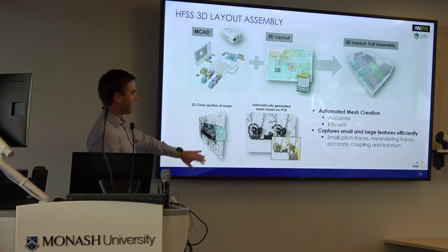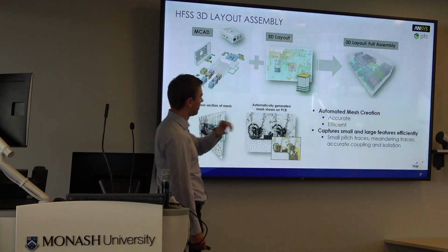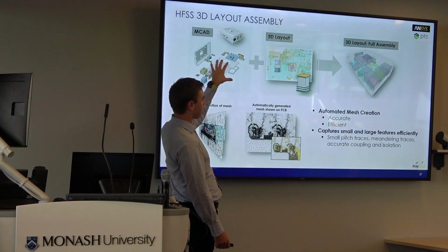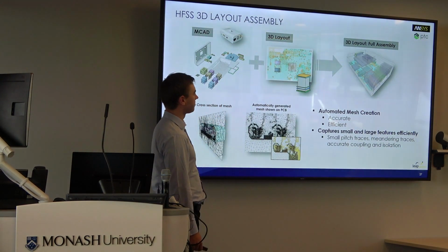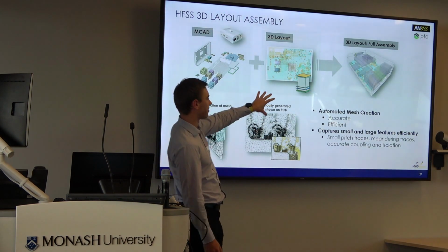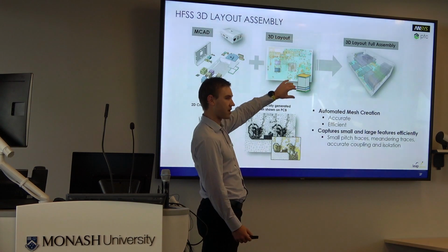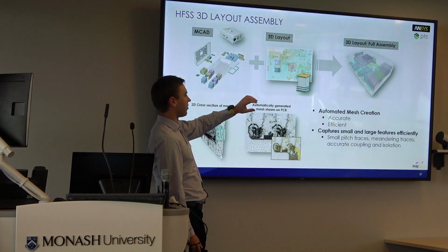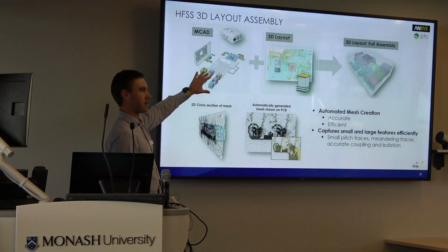For everyone doing PCBs, particularly in HFSS 3D Layout, it used to be that the worlds of mechanical and PCBs were quite separated. It was hard to solve both at the same time. Now you have the option to do what we call full assembly, and so you can solve a 3D layout problem with all your ports, import your ECAD and do the stack up. But when you want to do the final assessment, you can drag and drop an HFSS design straight into it.